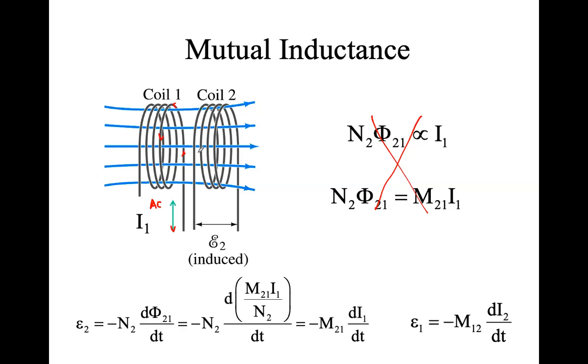I guess the result of that is that coil 2 here sees a change in magnetic field, and it has a cross-sectional area right here. So it sees a change in flux, and that change in flux is happening very rapidly over time. And so the rate of that change in flux induces an electromotive force proportional to the rate of change of flux. And the notation here is that's coil 2 because of the magnetic field, which is changing due to coil 1. And that's what we're talking about.